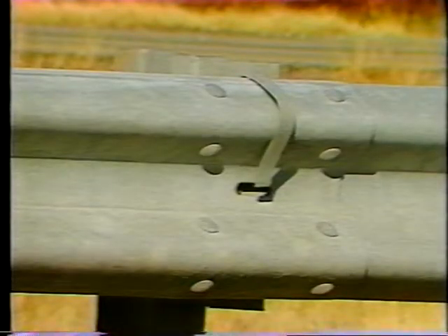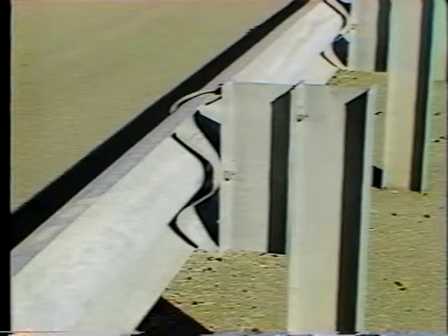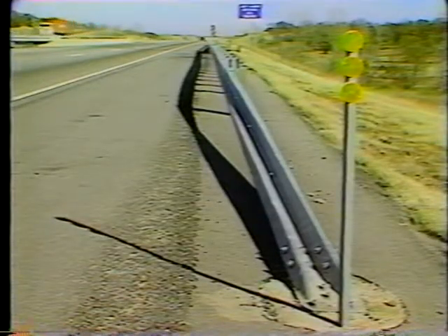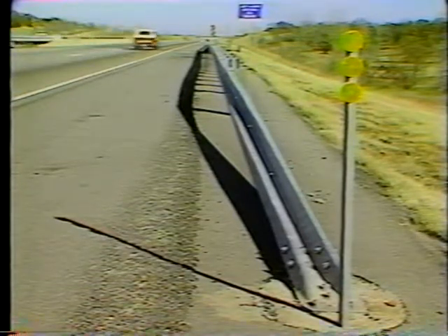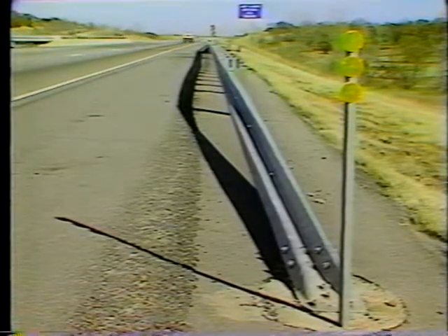Fundamental to the system's working as designed is the requirement that the rail release from the supporting posts as soon as the end treatment is loaded with a downward force. Various rail post connections are used. To set up the system, a short section of W-beam is bolted to the posts. The barrier railing is then placed into this section and rigged to be held there by a weak galvanized steel clip over the top rib of the rail. Any significant downward load on the railing, such as the weight of a car, pushes the rail down from this connector and allows the W-beam to fall harmlessly to the ground.